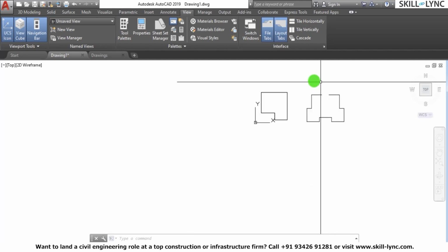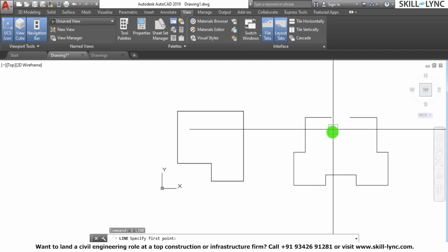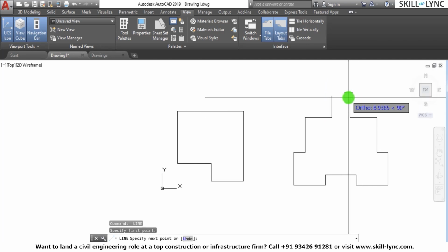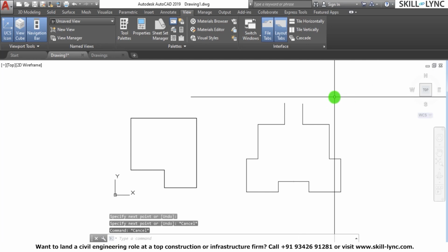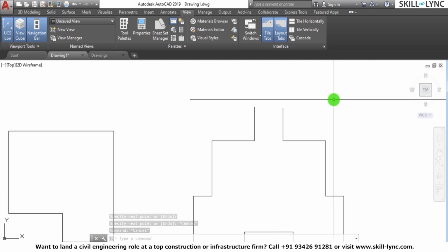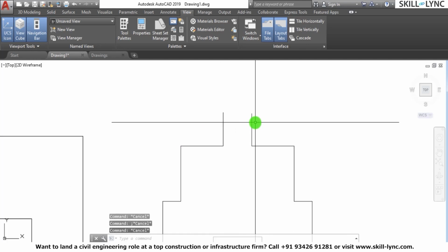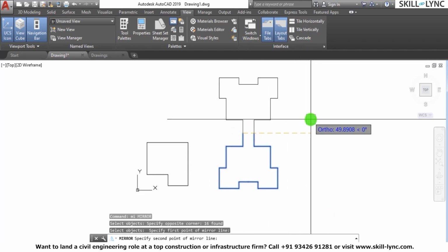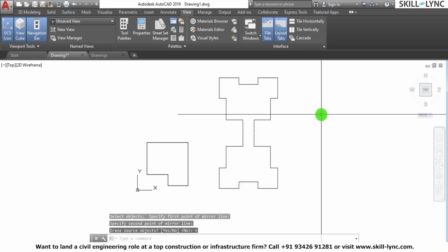One thing that is sure is that the 2D mirror is the command used when you are taking a line and mirroring it. In the 2D mirror, the only thing you can do is mirror an object, or create a replica of that object, over an axis, not a plane. So if you want to mirror this particular object, using 2 points you can define an axis and mirror it.